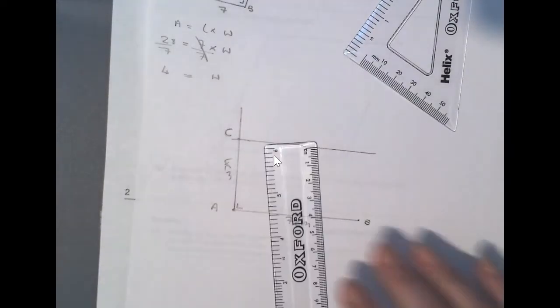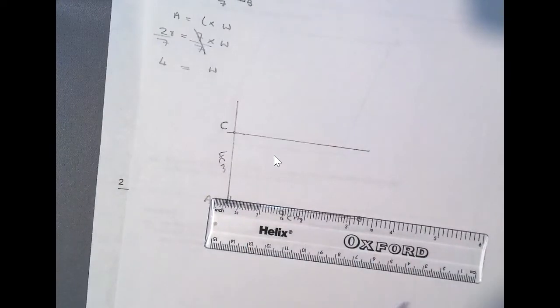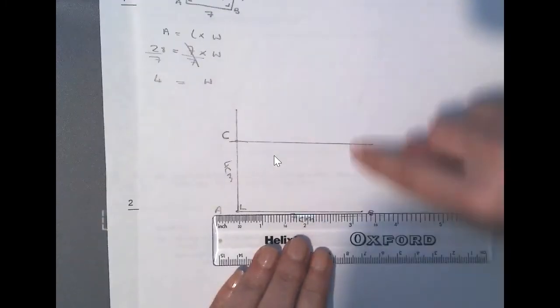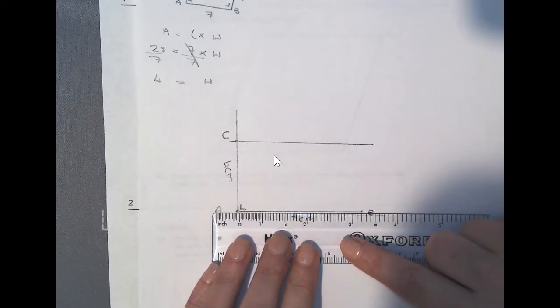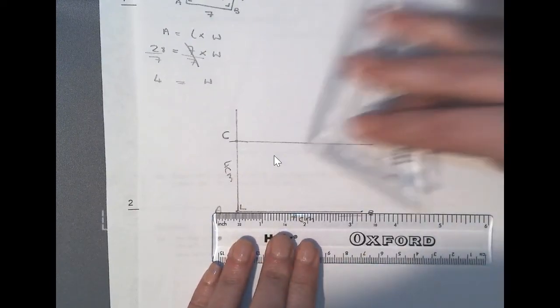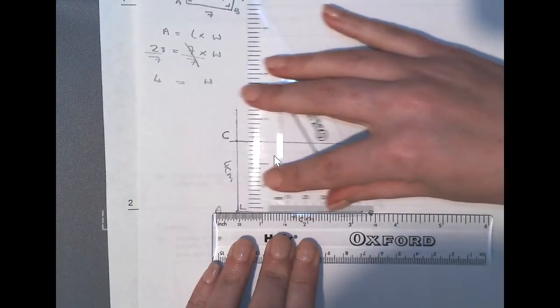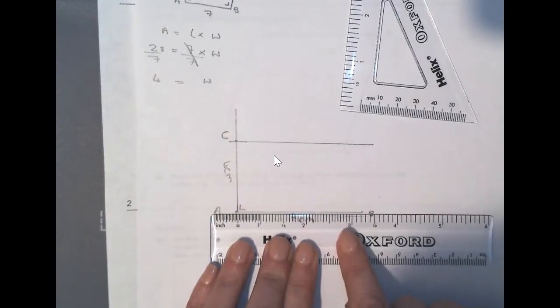And then you can, of course, do the same thing on the opposite side. So I'm holding my ruler, and you can see your ruler goes the opposite way to the line that you want to draw. So my ruler now sits on the bottom, and I'm going to slide my triangle this way instead this time. Your ruler goes the opposite way to the line that you're drawing.